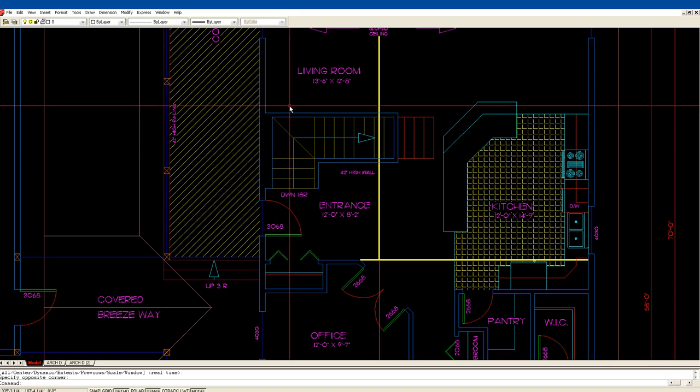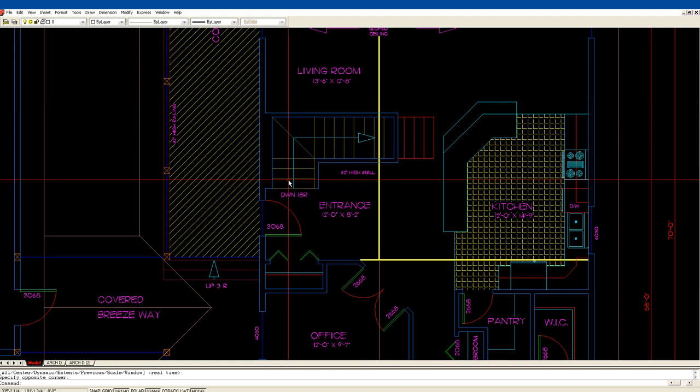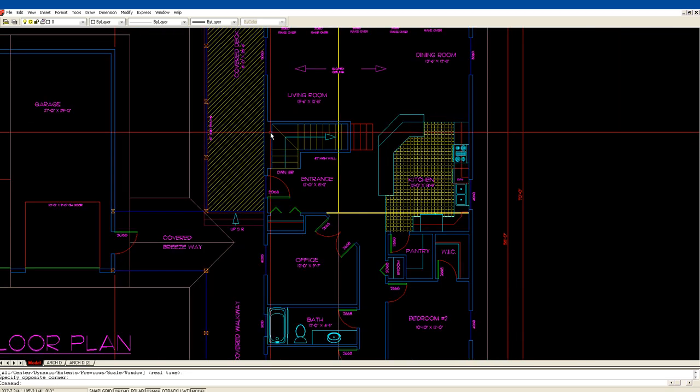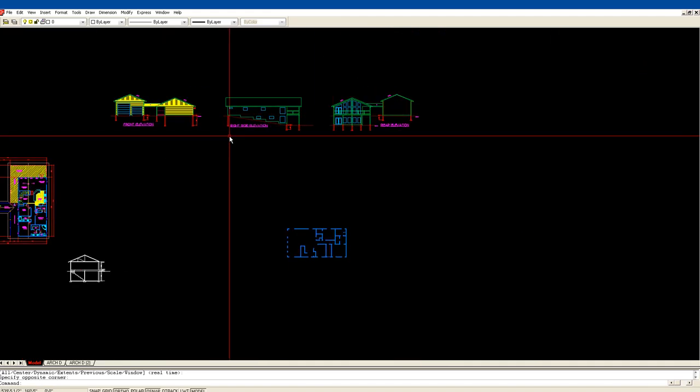When you go downstairs into the basement, it's an 8-inch wall. And of course, these stairs run right by it. And so that's thicker. Plus, you want another 2x4 wall built on the inside of that so you can insulate it. And so that's why that becomes so heavy here. Now, he's only going down 1, 2, 3, 4, and then 5 risers that affect this. And when you're looking at his elevation, okay, he's building into a hill.